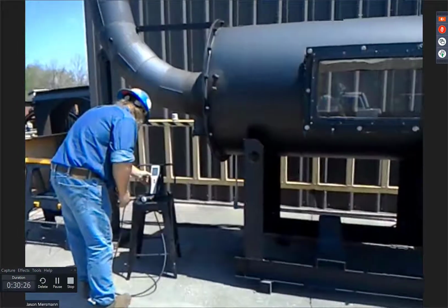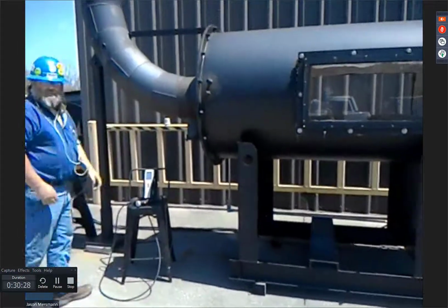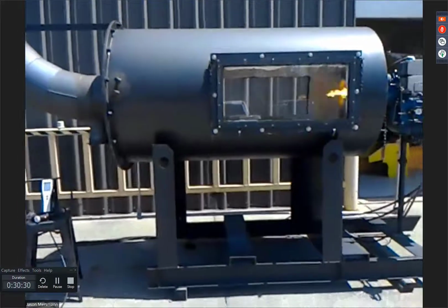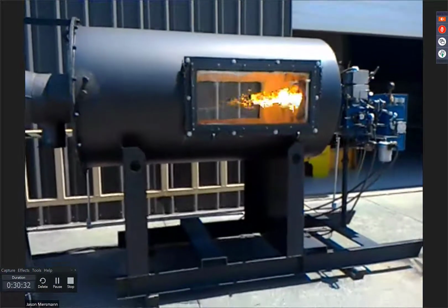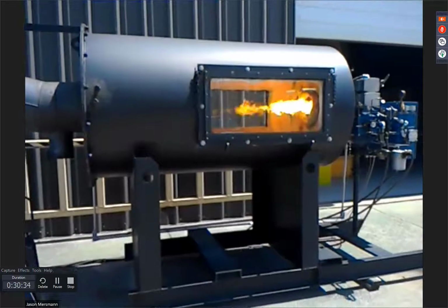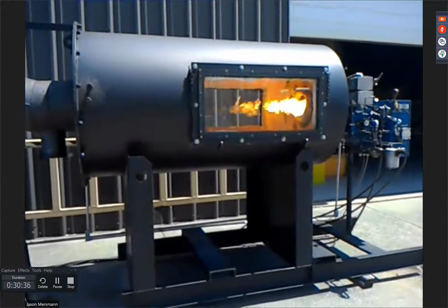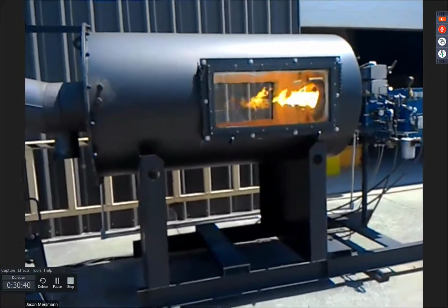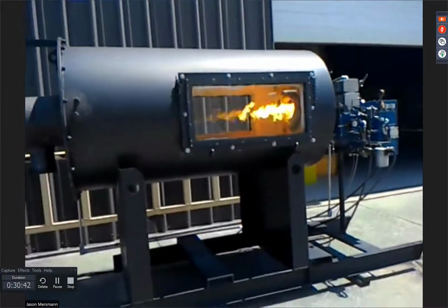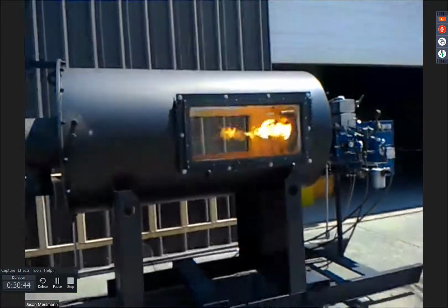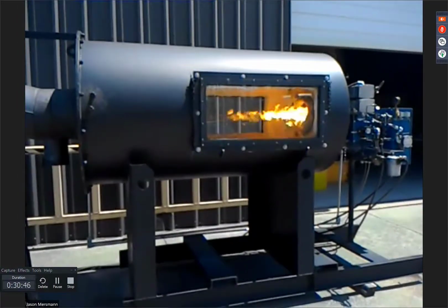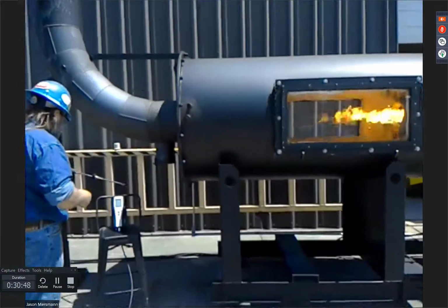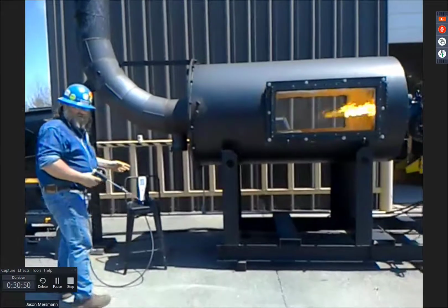Right now, what's happening is the system is working on the purge. I have everybody muted because it's going to be really loud. And there is a flame. I have you unmuted, Kevin. Kevin, is that right now a kind of a bad flame? Right now, that's kind of a bit of a neutral flame. I'm going to put the probe into the stack, and I'm going to show you exactly how it changes.